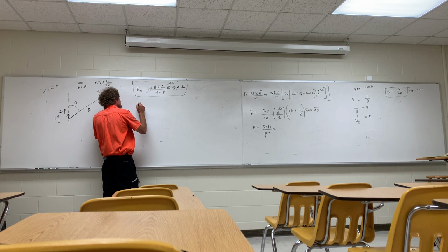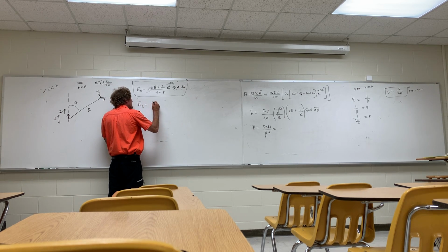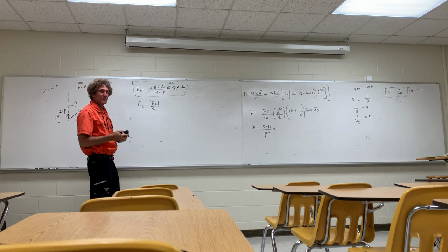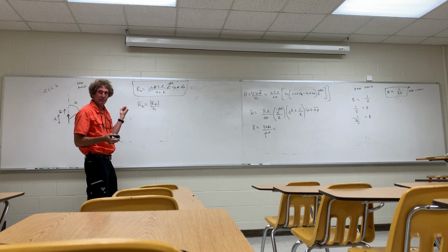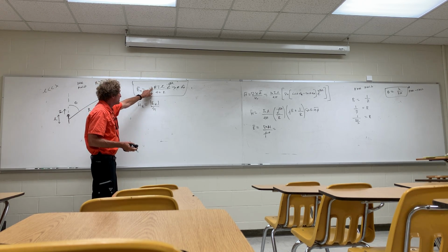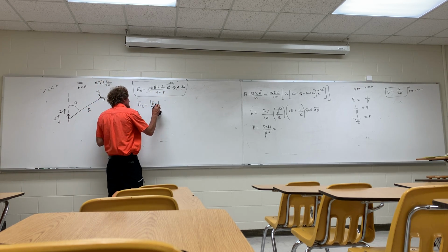The H field, if it's radiated, you can always get by just taking E radiated and dividing by eta. You know the relationship for any plane wave propagating, you take the E field divided by eta, you get H, right? So basically you take that equation and just get rid of eta, and the vector direction becomes a phi. So I'll write that down.